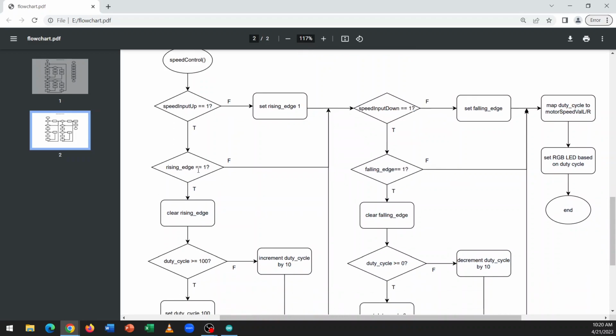So you go into the next check, which is the flag check. What does this flag do? It basically means that there was no button pressed before, and now there's a button pressed. So there's going to be a rising edge from 0 to 1 when you press the button. But in some cases, because these are mechanical devices, there will be mechanical noise. So when you press once, it doesn't mean that inside it's only one press. It could be some noise, and it can register multiple presses, even though you only pressed once.